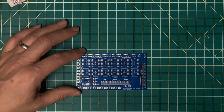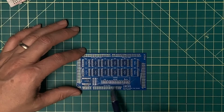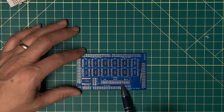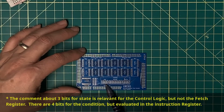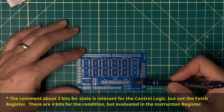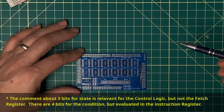The Silkscreen is not exactly the way that I had intended either. At some point I was using 4 bits for state and 4 bits to indicate what was going out onto the main bus, and then the remaining 8 were going to be the instruction. I realized very quickly that that severely limited the build, so I changed the upper 3 bits to be state and then 12 bits to be the instruction. And so the Silkscreen is absolutely incorrect and needs to be corrected.